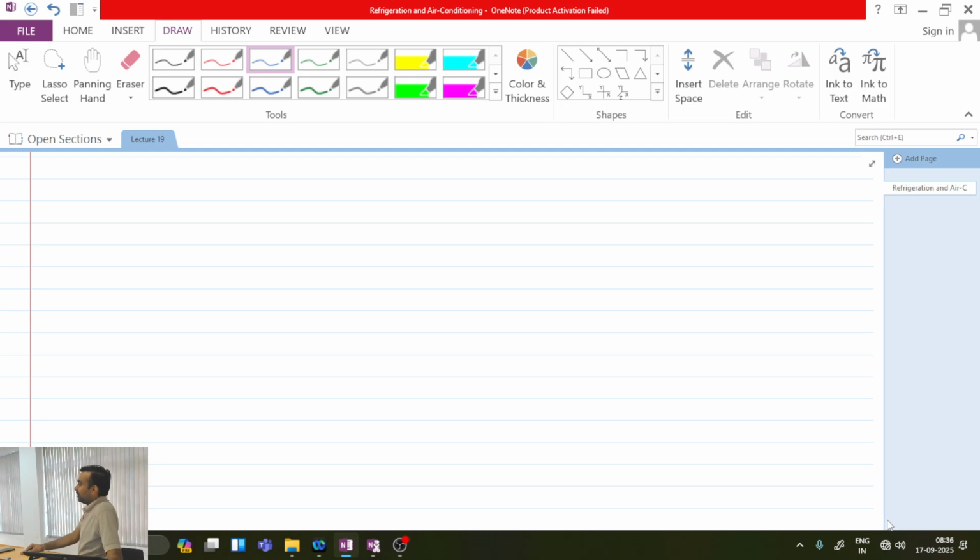If for the same fluid I have to determine property in the saturated state, then how many are needed? Only one. Fraction should be known, but by just knowing either pressure or temperature, I can determine all other properties in the vapor as well as the liquid phase. For a mixture I need fraction, but for independent phases only one property will be required.